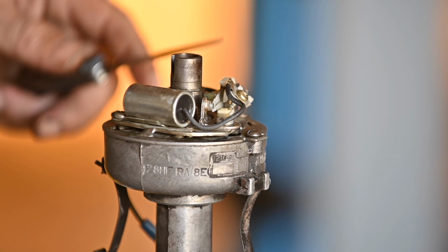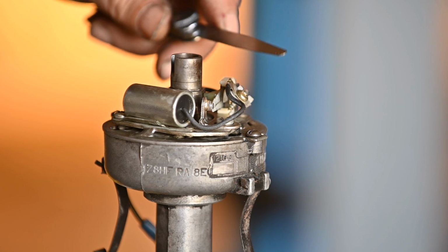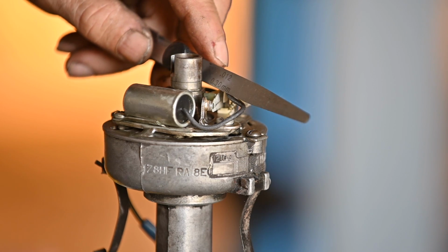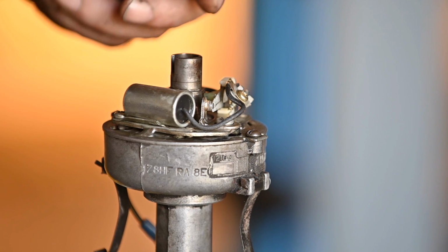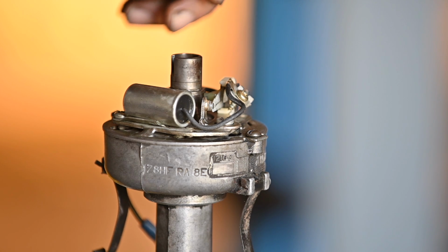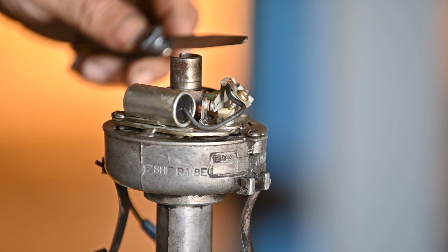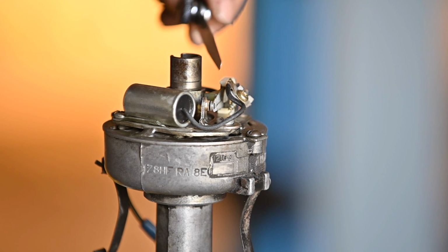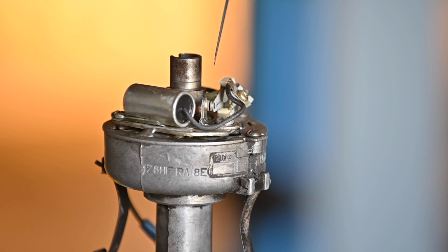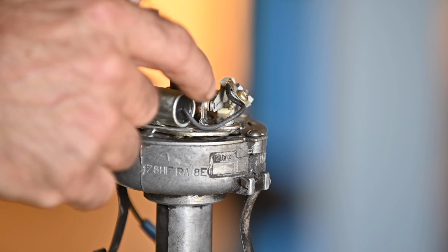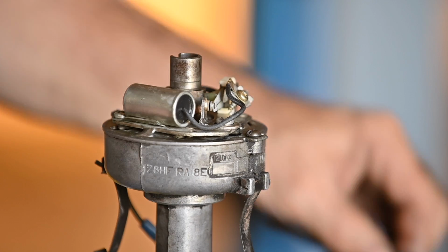Adjusting the dwell angle is easy. It's a manual thing. You need a gauge of a certain thickness, and I'm using a 0.3 millimeter gauge, but that depends on your engine specification, and I know in general that 0.3 is about right. So I'm going to rotate now the engine until the notch is pushing these breaker points to the maximum possible opening. And then I will use my gauge and stick it in there and feel that it goes in properly. If it fits like this, then it's properly adjusted. If not, then you will have to release the screws and adjust actually the breaker points.